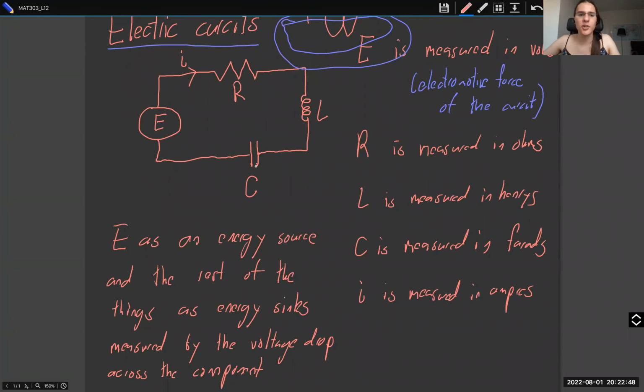Now how a capacitor works is that it literally sort of breaks the circuit. These two sides of the capacitor are not connected. But the thing is that they're very big. So as the current flows, this side can accumulate a large positive charge and this side can accumulate a large negative charge. Overall, it's going to be neutral. What a capacitor usually looks like is you take two sheets of conducting metal, put an insulating sheet between them, and then roll it up.